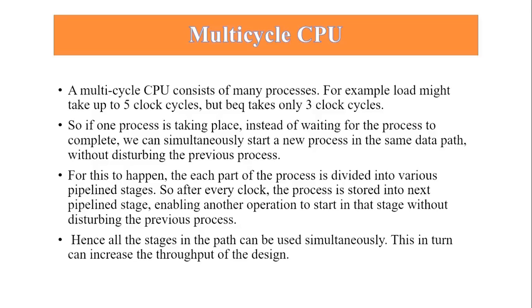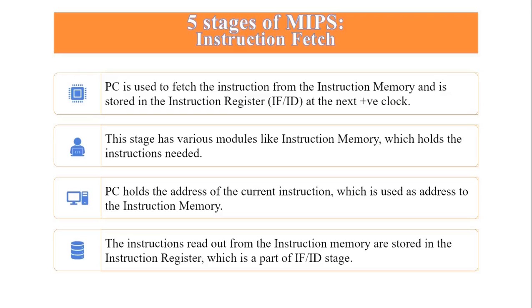Each part of the process is divided into various pipeline stages. So for every clock, the process is stored into the next pipelining stage, enabling another operation to start in that stage without disturbing the previous stage. Hence, all the stages in the implementation can be used simultaneously. This can also increase the throughput of the design.